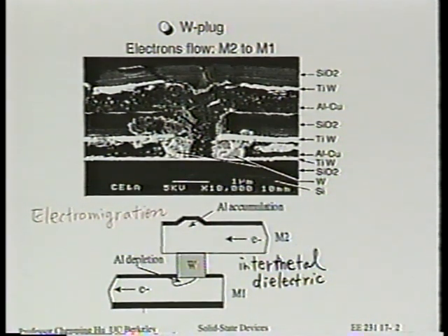Well, it turns out that tungsten itself has a better reliability than aluminum, all right? And in the via, sometimes we are concerned about the current density in the via itself, so tungsten is good. Tungsten deposition in the via hole also historically was studied very early on, and has worked quite well. And so people like to use tungsten, so tungsten continues to be very popular.